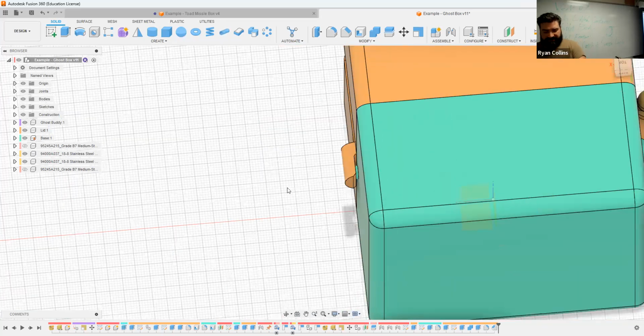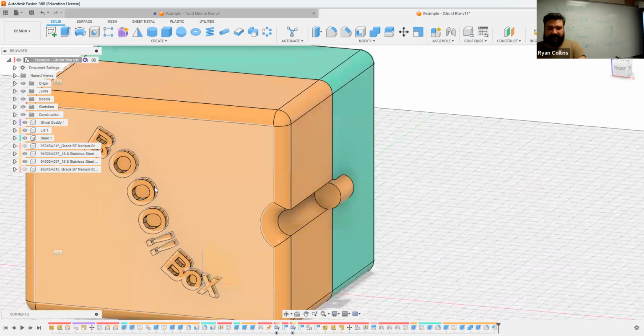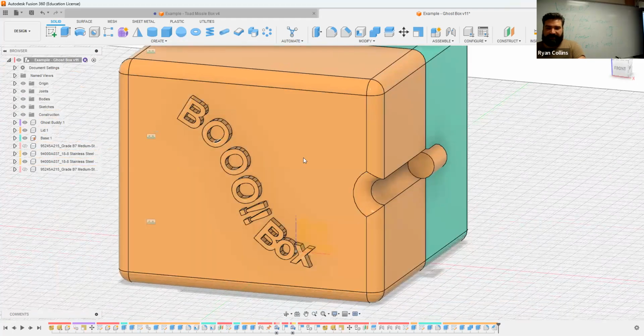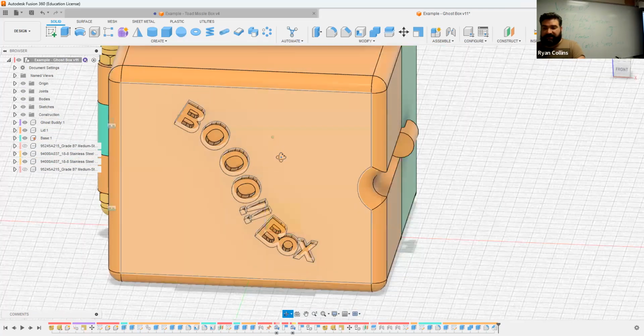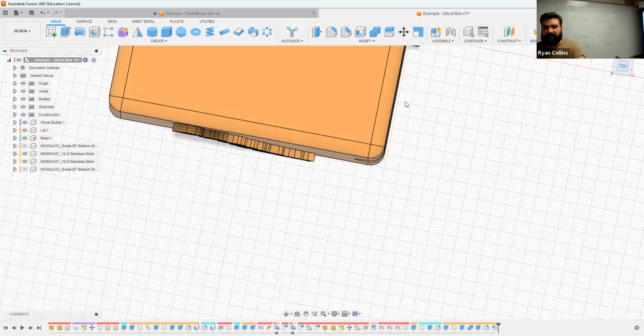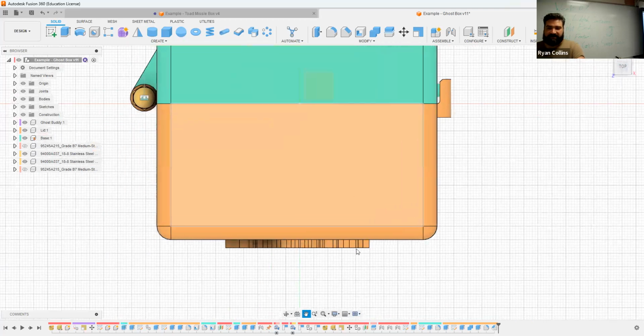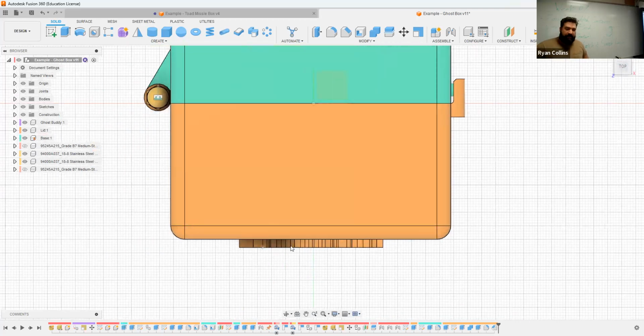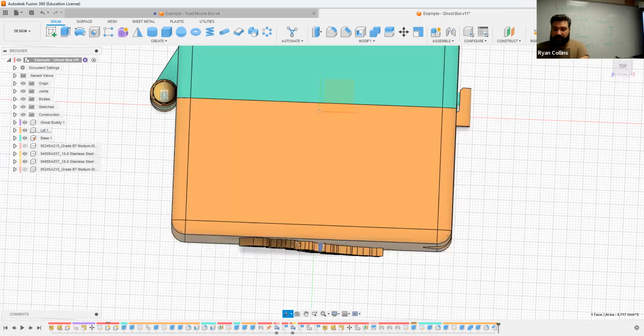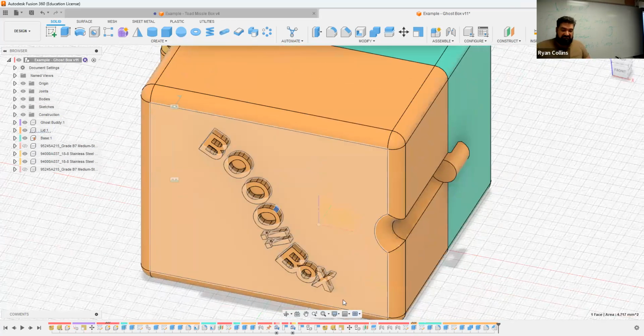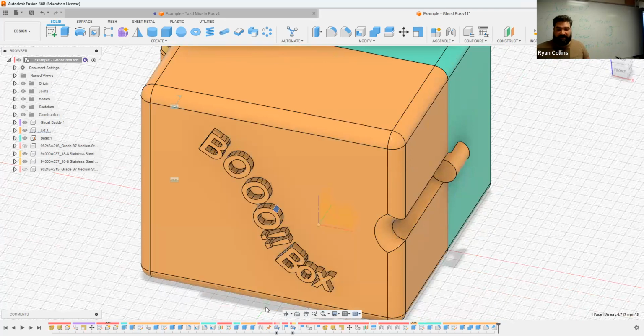The other thing I want to show you is just some other features. Things like, if you're printing this, orientation. Ideally, you'd probably want to print this, now I'm going to show from the top down, but essentially in this orientation. But that might mean that in reality, maybe the extrusion for your text shouldn't be positive. Maybe that should be negative.